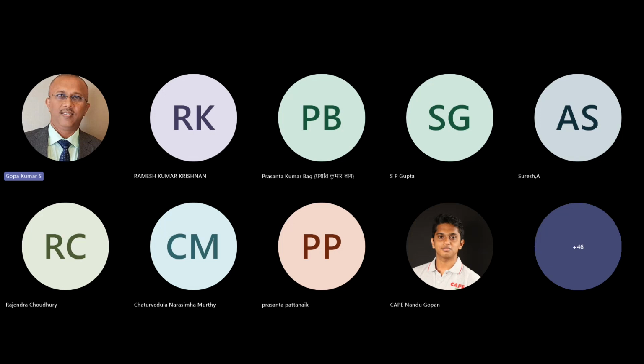Sir, actually, earthing is only a term, only a name. For the consumer premises, consumers have R phase, Y phase, B phase, and a neutral. And the fifth one is earth. Only the name is earth; it's a conductor. All earthing means connecting the metallic, non-current-carrying parts to that conductor. If you look at IS 732, the definition of earthing is connection of exposed conductive parts to the MET, that means a common bus bar. That means you have the fifth wire in a three-phase system, and that fifth wire should interconnect every exposed and extraneous non-current-carrying metal part of the installation to a common bus bar.